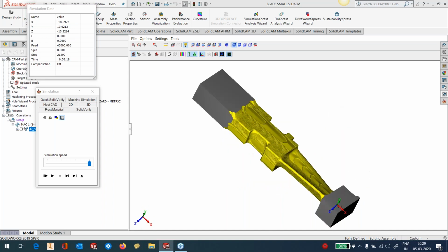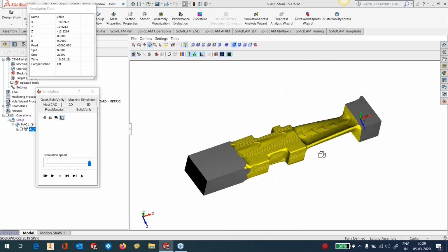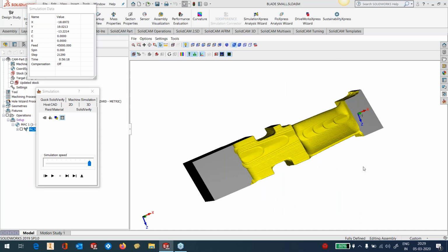So there you can see turbine blade roughed out in 4-axis. Screw machining. So like I said, don't go by the word screw machining. It can do much more than just machine screws. It can do several parts. You can just think, any part rotating around X, this is a candidate for screw machining. I can do roughing with it very easily. Any part machining around Y-axis, 4-axis, it's a candidate for screw machining. So it's a very, very powerful function. Don't limit it only to screw machining or extruded screws. You can use it for several other parts which need roughing and finishing.